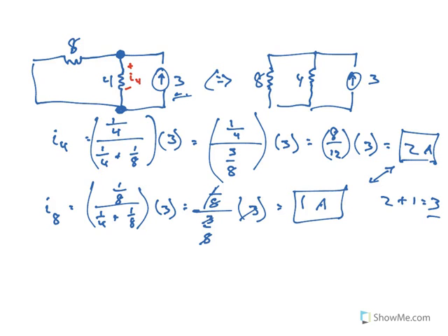So there again, if you run into the situation where you have a circuit, all the resistors are in parallel, and you want to know how much current is on one of the particular branches, this current divider technique allows you to do it a little quicker than if you were to do Ohm's law and all the mess we've been doing in the past. Now the next technique I want to talk about is called the superposition principle.